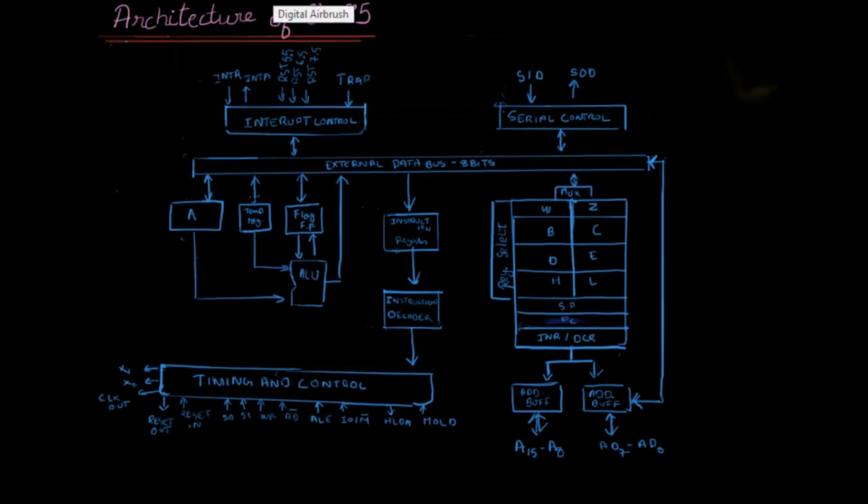And this program counter holds the value of the next instruction. It sends this particular instruction, forget all other concepts, okay? We have the address value. It's a 16-bit register. Remember, the program counter is a 16-bit register. It sends this address through the address buffers. Okay, these are called the address buffers. This and this are address buffers. Okay, it sends the address through this address buffer.